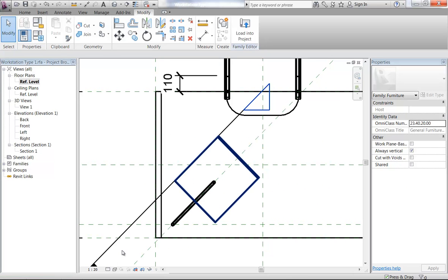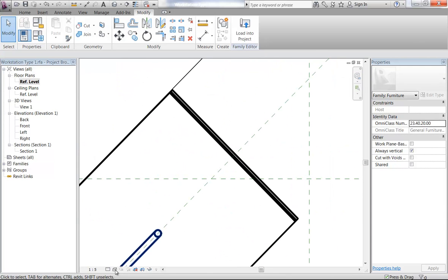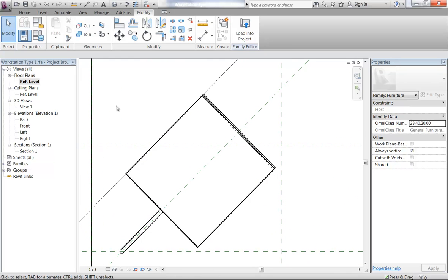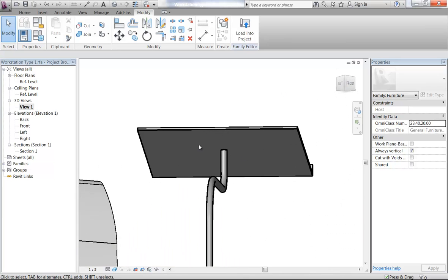So here, I'm looking from above. I'll change the line weight again so you can see what's happening. So I'll go to hidden line as well, and you can see there's the front of my stand at the angle. And so I'll just do a very simple extrusion on top of this, or maybe, I know, I can do a revolve. Yeah, that'll be really good because I can do that underneath actually, and that'll look excellent. So in the 3D view there, I'll just show you underneath. So I'm going to do a mounting under there, which will be a revolve, and so I'm going to draw that on the underside of this surface now.